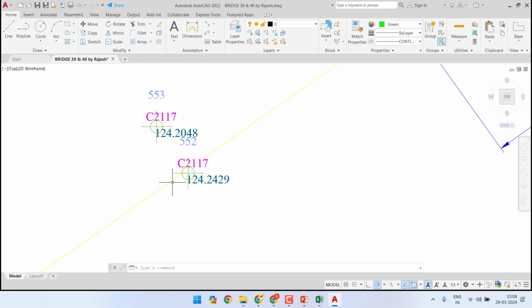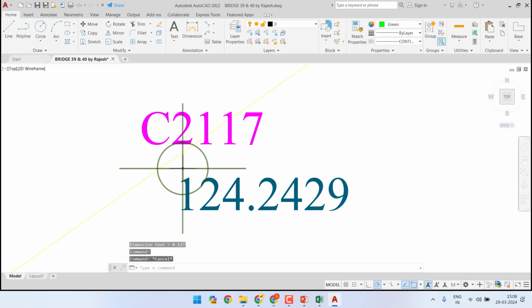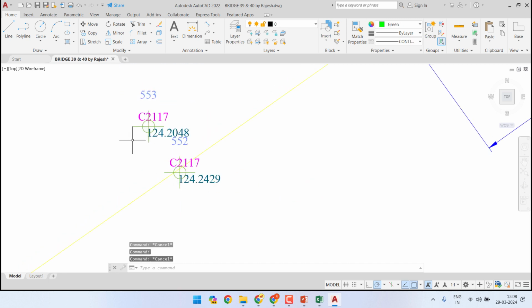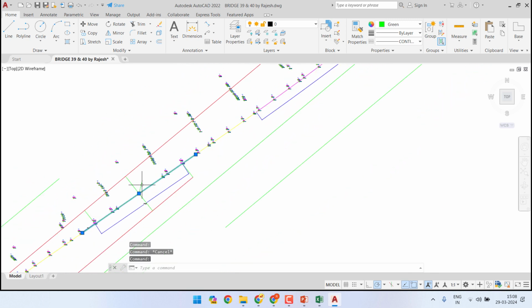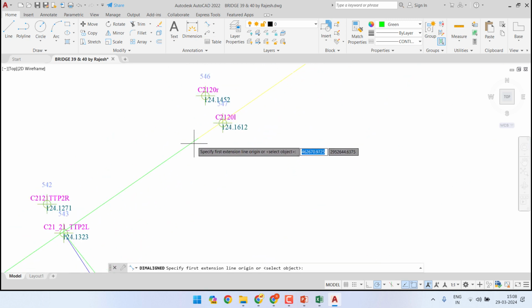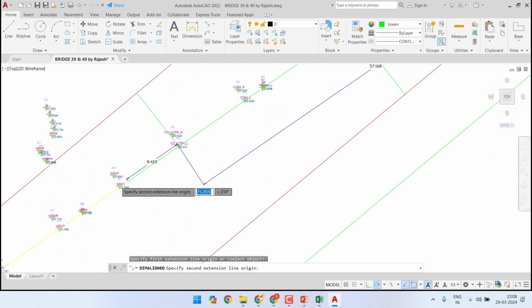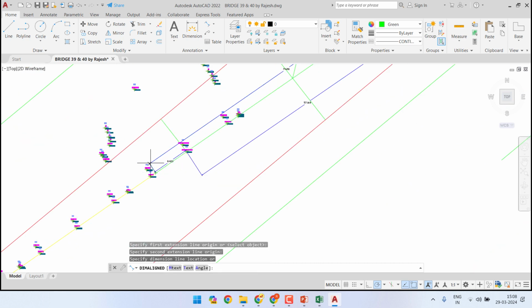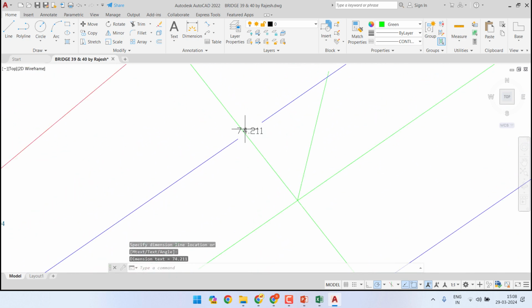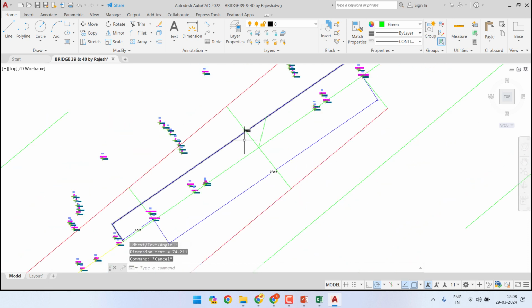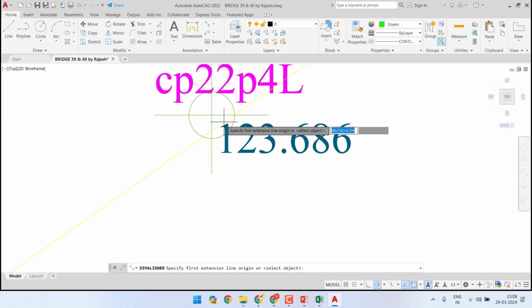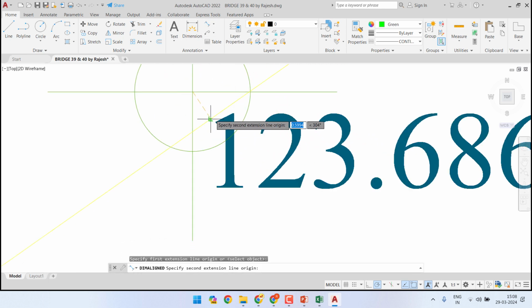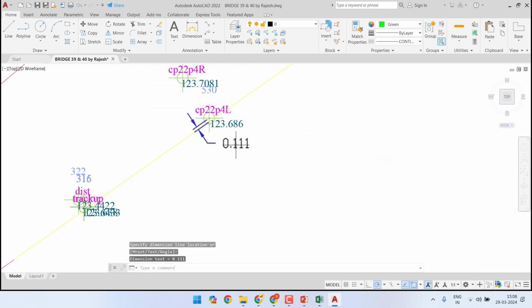This is the transition portion. Again here also the new curve is away from the present position, and this is going right side, so away from the OHEs. This is the middle straight portion. The length of the new middle straight portion has increased. Earlier it was 57 meters. Now it will be 74 meters. And let us see in this case here, the track is going towards the OHE mast, like 111 mm.